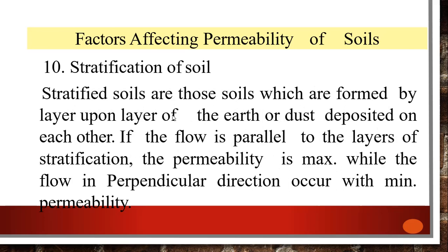Stratification of a soil. Stratified soils are those soils which are formed by layer upon layer of earth or dust deposited on each other. If the flow is parallel to the layers of the stratification, the permeability is maximum, while flow in the perpendicular direction occurs with minimum permeability.